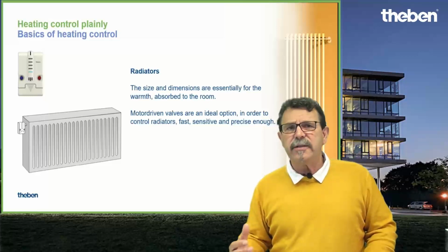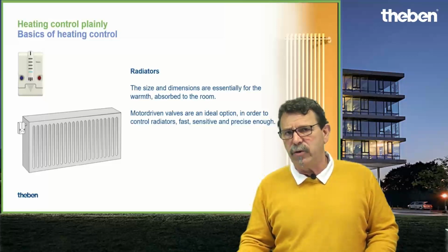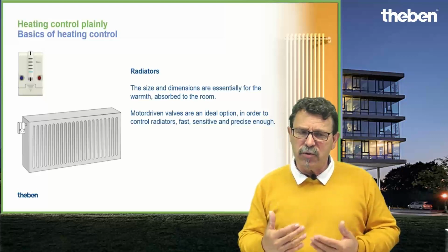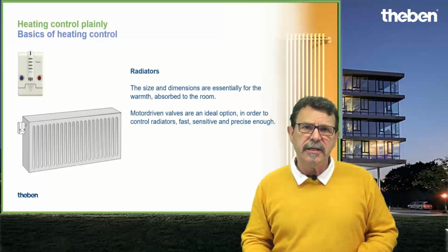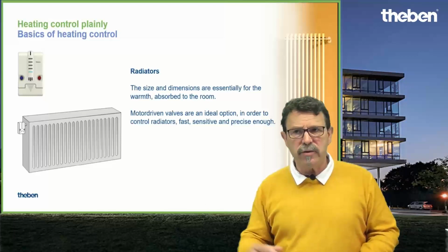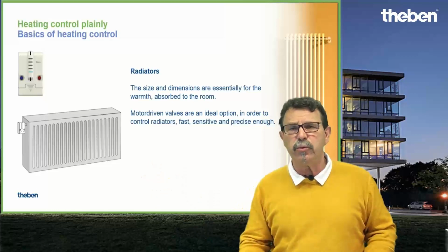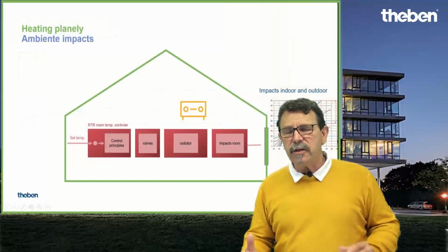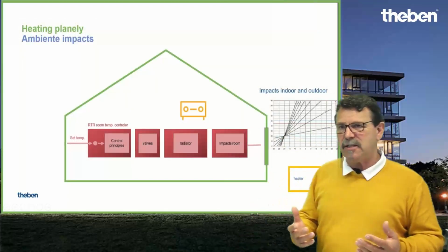Terminal valves we recommend for warm water underfloor heatings, because warm water underfloor heatings are, from their control characteristic, rather slow in comparison to these radiators, which we have here on the left-hand side. So how is the control principle, finally?